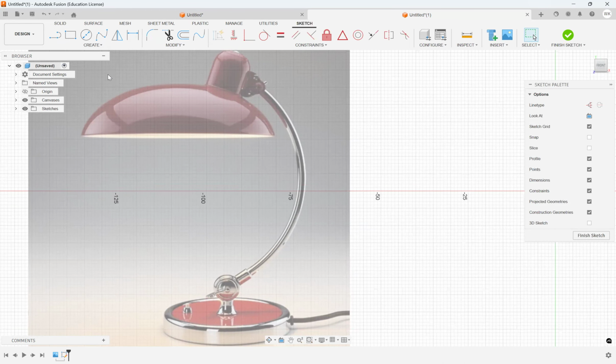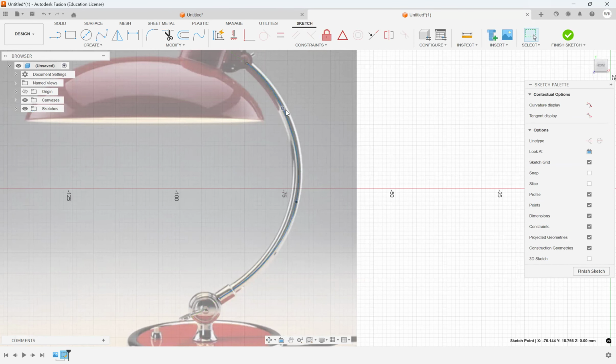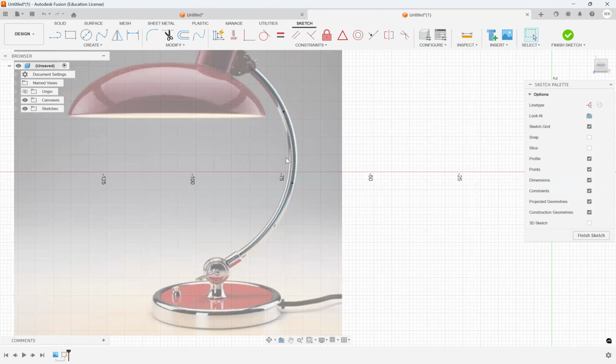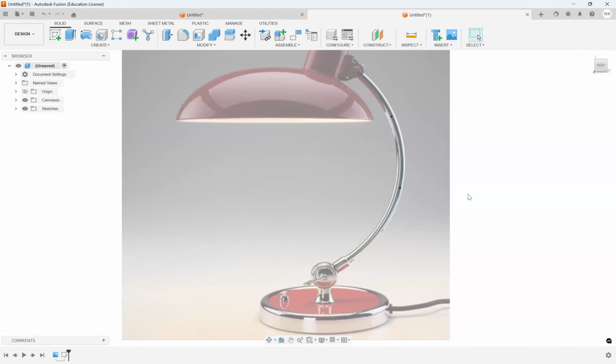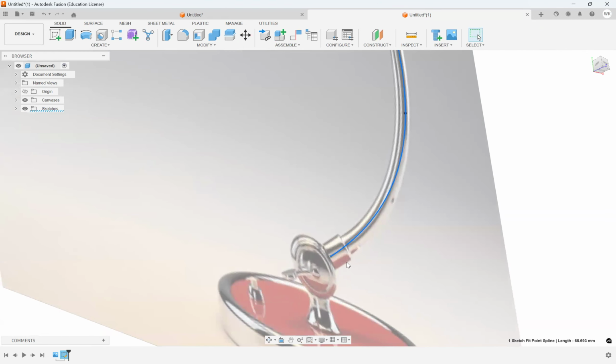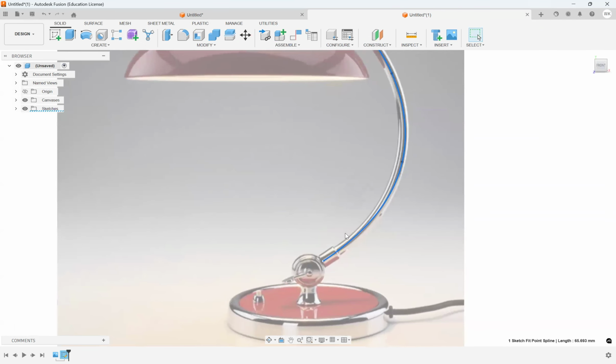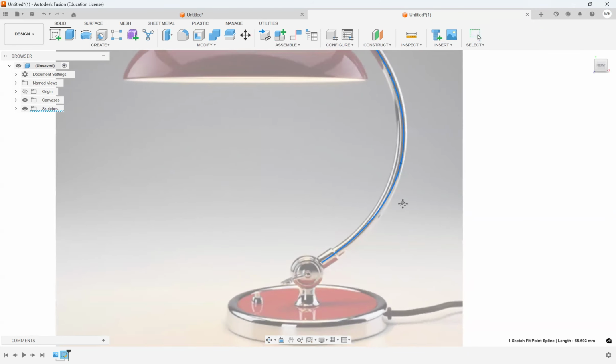So in our case, this center line in here will be the center line that we will try to create, and as you can see, it will follow along the center line here. And the second one is that we need a profile. The profile is the side section view of this pipeline, which follows along these curves.